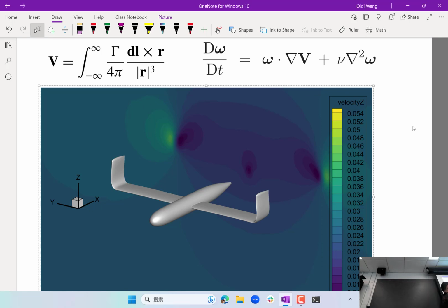One of the ways is that it generates thrust, right? Because you have a strong tip vortex coming out of the junction between the wing and the winglet, the induced flow on the winglet goes inboard, right? And if the winglet goes downward, it will be going out. But for a winglet like this, it goes in, okay?